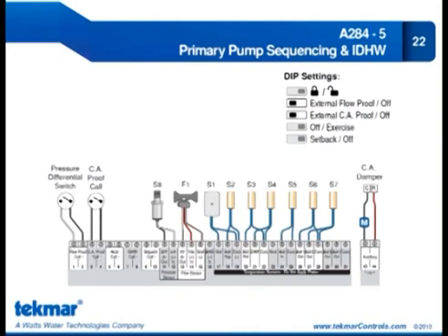Right, and just to clarify, because there are different protocols out there, Modbus is probably one of the older ones, and the physical layer for Modbus basically uses an RS-485 circuit, and that's typical in old buildings.